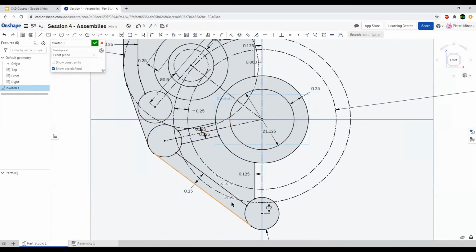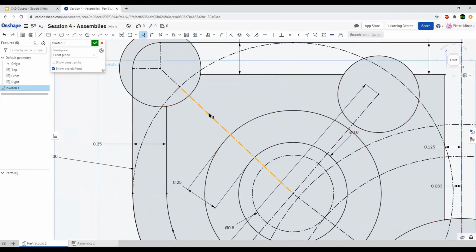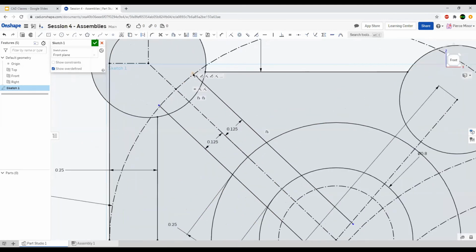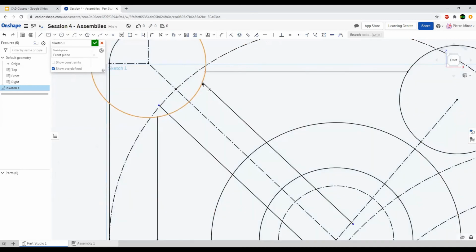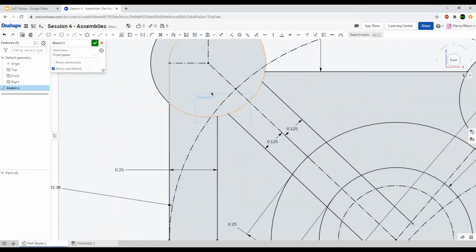Now, we could do some. Oh, actually, I need to do the same up here. Hold on. All right, so that goes there. And then we're going to use the offset tool again. The key for that is O, by the way, in case I forgot to tell you that, which I very well might have. So we are going to create another line, same as before. It will be 1/8 apart. And then same as before, we're going to create a second line, the opposite direction, that is also 1/8 away. And that's not what I want. And now I have these lines, I can grab the point. Same thing I did before, where I just, there's so many constraints, where I just drag it onto that line and it attaches. Do that over here too.